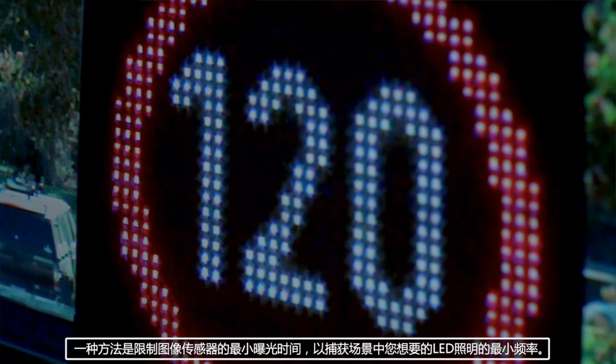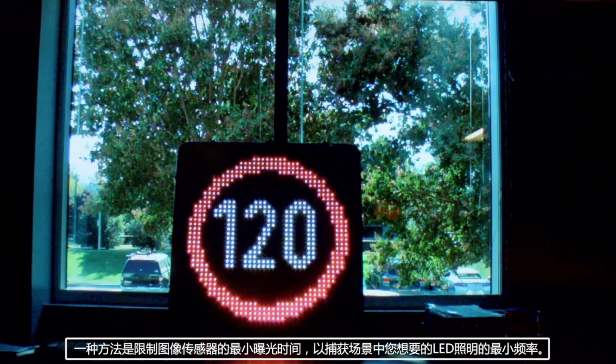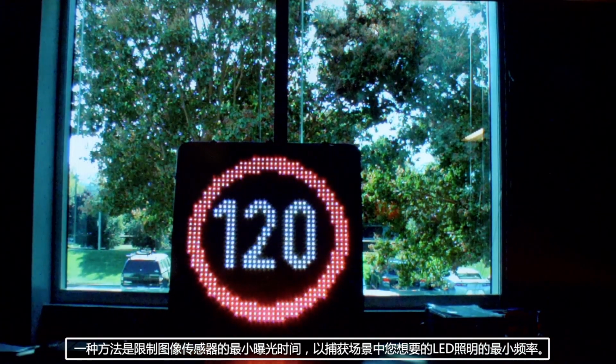One way to guarantee that pulsed light sources are not missed and you don't get the appearance of flicker is to capture the LED pulse in every frame. One way to do this is to constrain the minimum exposure time of the image sensor to capture the minimum frequency of LED lighting that you expect to have in the scene. The problem with this is that with a limited dynamic range in a single capture, when you increase the exposure time, you're going to blow out the bright areas of a scene.